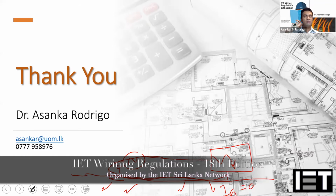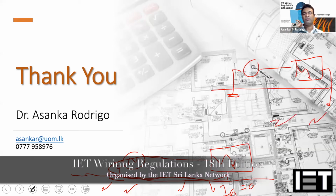But as I said, if you have a TT earthing arrangement, when you have something like that, you will see current goes to the ground. So in that case, this is where you are looking at your RG value, having a lower earth electrode resistance, because that can create a ground potential rise. Otherwise, in here, you don't care about the earth electrode resistance value. Even in a TN system, you don't care about your earth electrode value.